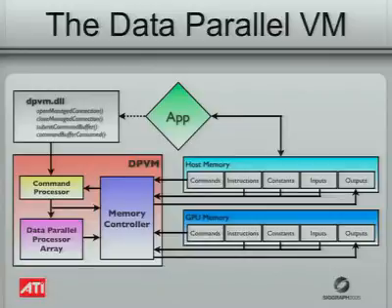The application also has access to all the memory resources on the card, including GPU local memory, which only the graphics hardware can read and write to, as well as host memory, or PCI Express shared memory, which the application and the graphics card can read and write to. So in this sense, the application submits all of its data through the shared memory or the host memory, and then the graphics card can either use that for inputs, outputs, or results. And also in our model, memory is just memory, so instructions and commands and constants, inputs and outputs all get stored in all of these memory pools.